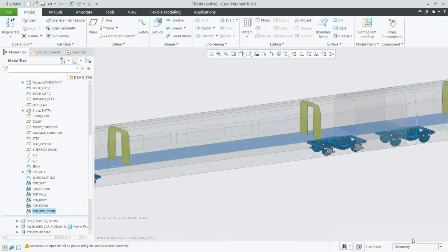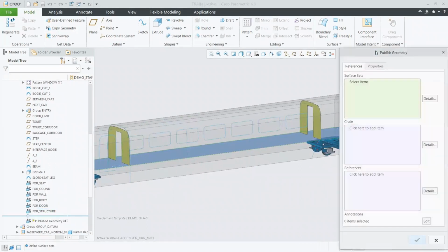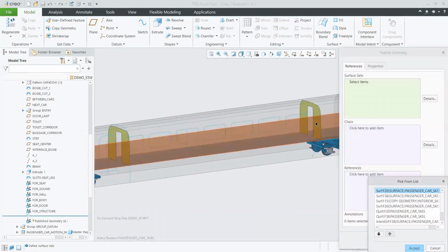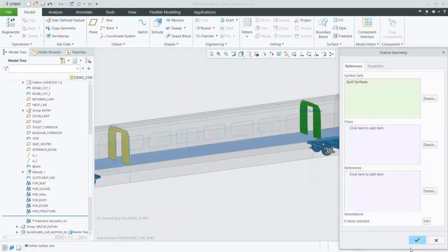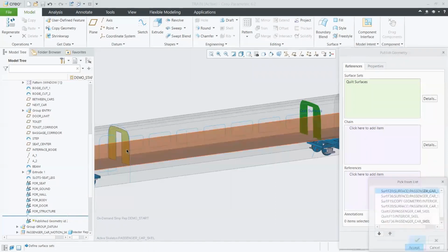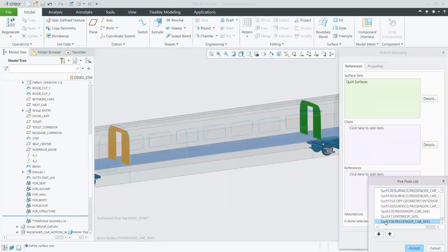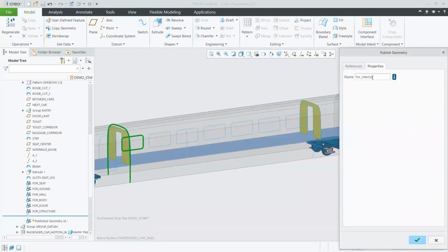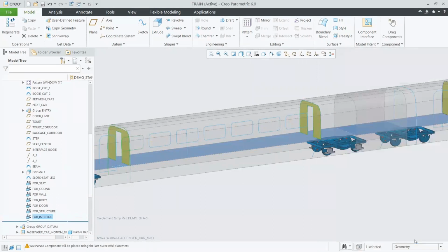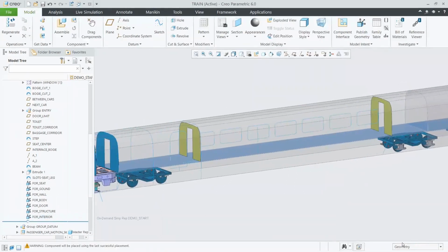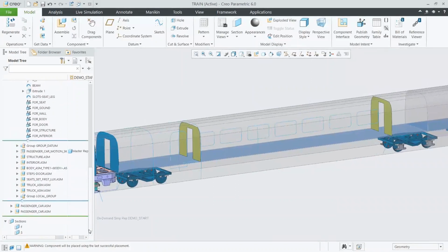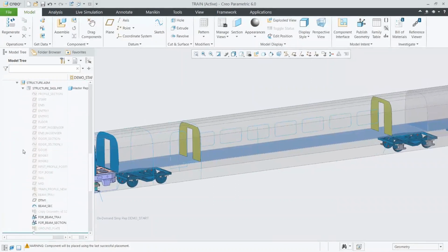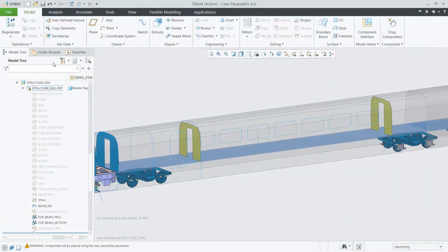And then even using that same skeleton model, we'll go ahead and create another set of published geometry. Maybe in this case, it's going to be for some of our interior components. So we might take a few other sets of curves. It's really whatever makes sense. Lines, arcs, points, whatever references that you're going to use downstream. And our interior might be useful to get that door frame or the window frame. And then we'll publish that out for our interior components. And so that's what you'll see. We're specifically grouping that published geometry, giving them a name so they're easier to find later on. And we could feed those down to the different areas of the different users that would need them.